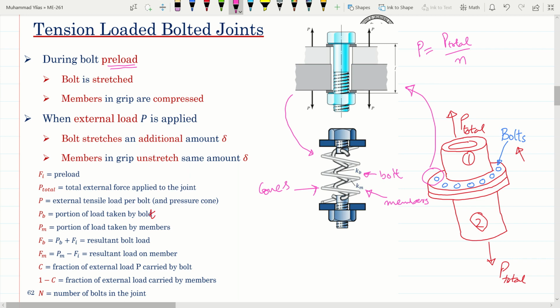For example, if we consider the wheels of an automobile, these wheels have to be joined with the help of bolts, and there is some preload which is necessary so that under the influence of vibrations and rotations, the wheels do not untie themselves and come off the vehicle. So we need preload for this joint to function.